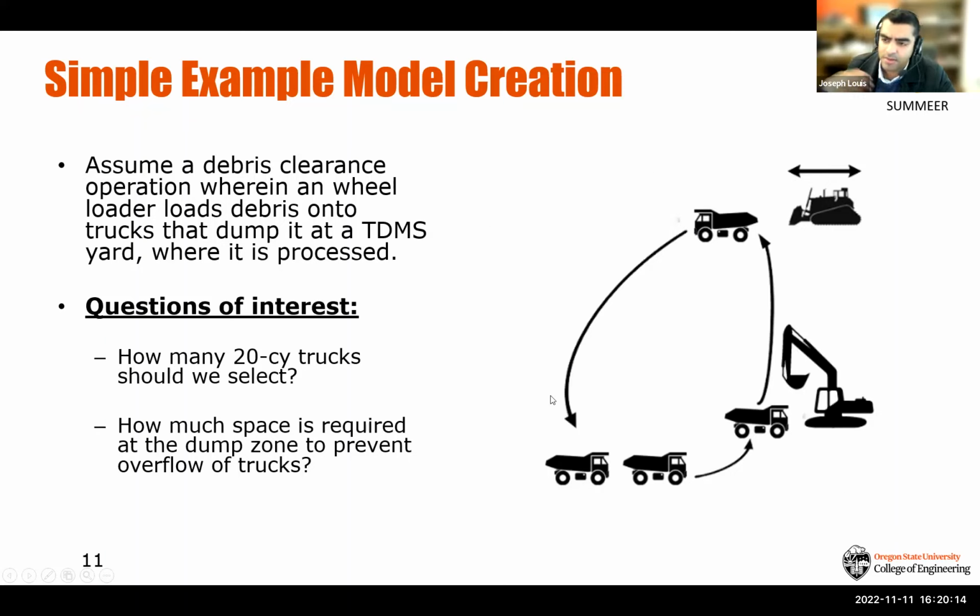So this is how these operations happen, right? Some questions that might be of interest for an emergency manager or for a contractor might be, based on the local site conditions, how many trucks do I need if the trucks have a capacity of 20 cubic yards? How much space is required at the dump zone to prevent the overflow of trucks? These are all very tactical decisions, right? We're trying to take into account the space constraints, the capacity constraints, and the types of resources that we have.